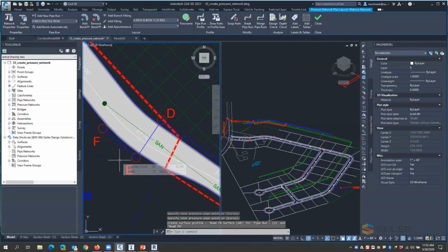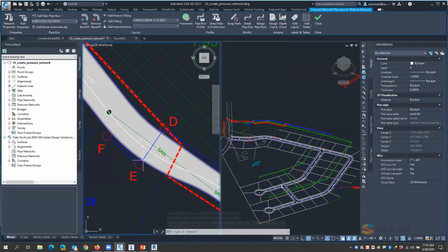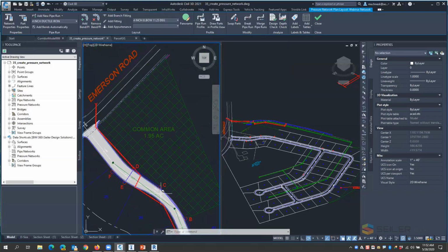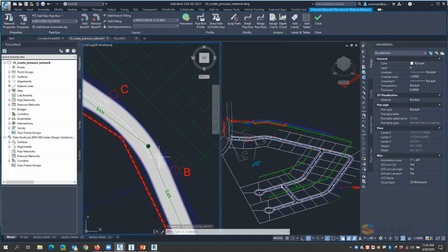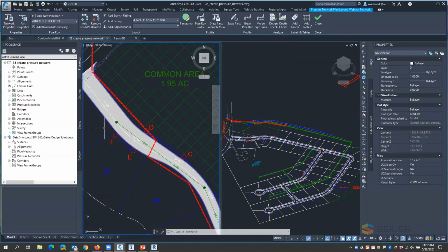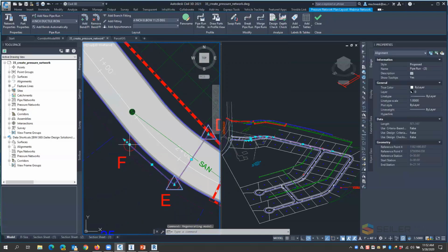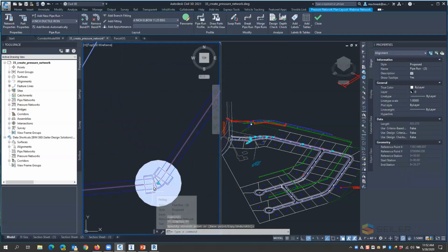It's also going to create an alignment along that pipe network. So you can see it's choosing the fitting without having to do any extra work. And where needed to, it's applying a deflection for the allowable deflection for those particular pipe ranges. And at any time, I can go ahead and select the fitting, change the angle of that pipe, and it will automatically go through and pick a new fitting for that.